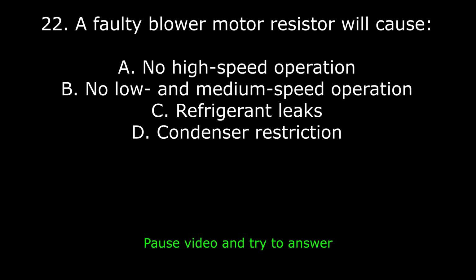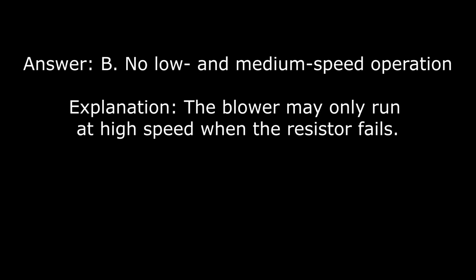22. A faulty blower motor resistor will cause: A. No high-speed operation. B. No low and medium-speed operation. C. Refrigerant leaks. D. Condenser restriction. Answer: B. No low and medium speed operation. Explanation: the blower may only run at high speed when the resistor fails.